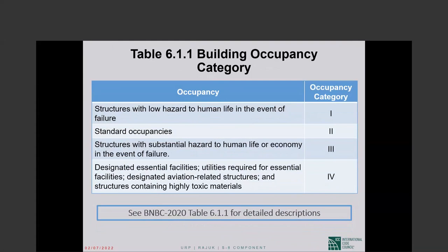the height limits for a structural system, like bearing wall systems could not be taller than 160 feet in seismic zone 4. The zone determined the level of analysis you had to do as the basis of design. In seismic zone 4 or 3, certain structures could not be designed based on equivalent lateral force procedure.